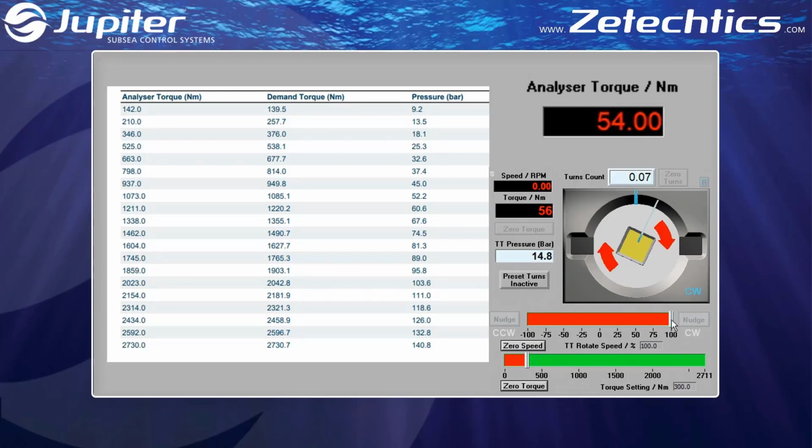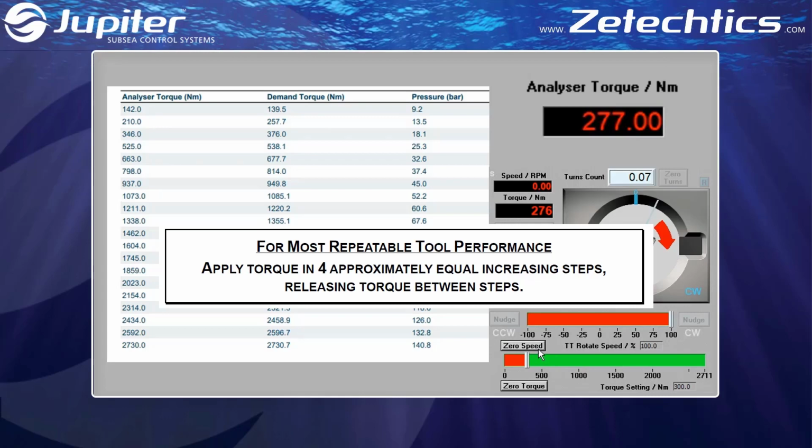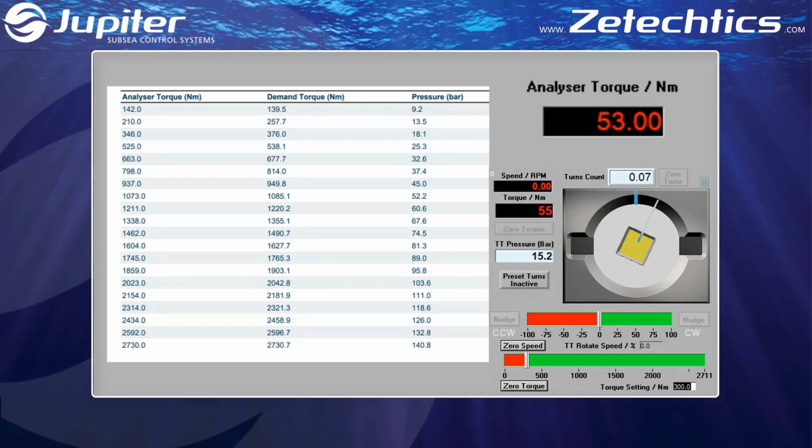The reason for showing these examples is to reiterate that the calibration is for the torque feedback only. Numerous variables prevent the torque demand being accurately calibrated for consistent results. This applies to all torque tool types. This is also why the torque tool manual has the displayed statement. Operating in this method helps the user prevent overshooting the required torque.